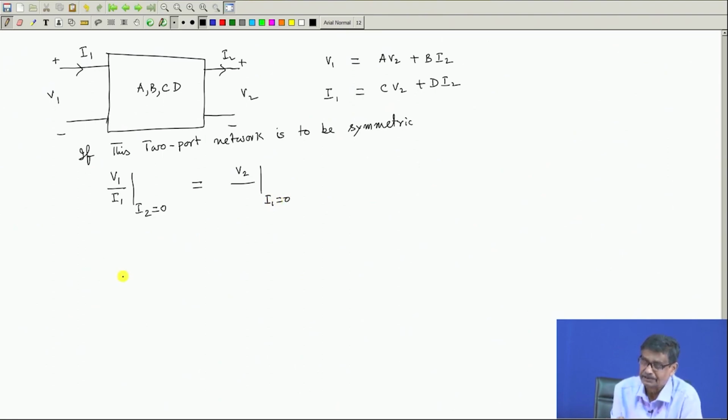But what should I write here? That is what I am telling. I must write minus I 2. The driving point admittance is this. This you must understand very clearly. Because of this surprise change in the direction of I 2 while describing ABCD parameters, this I have to do. But so far as the driving point impedance Z 22 is concerned, the current is to be reversed, because for Z parameters it enters. You have got the point.